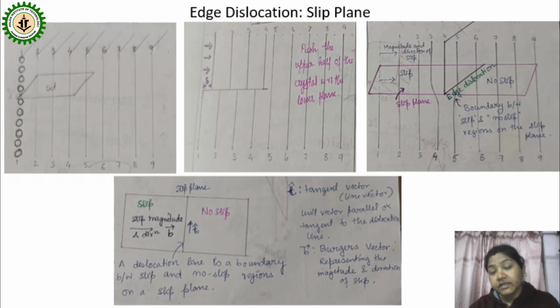You can see here the plane shown by the pink color. The left side plane is the slip plane and the right side plane is the no slip plane. Here you can see the distortion happens towards the Burgers vector, this side, left to right, but the tangent vector is from bottom to upward.